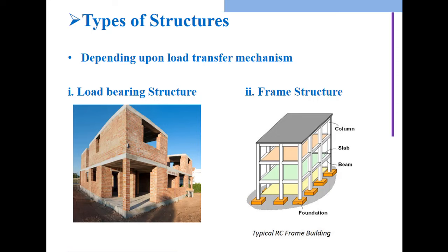Right? So as I told you earlier also, if you want to determine the weight of the bar in kg, you need to remember the formula, which is diameter of bar squared divided by 162.2. Why am I talking about these things? Because whenever you are going to assign the dead load, these things are very important. If you only select the dead load for the overall building, does it contain the weight of the bar? If the weight of bar is not considered during the analysis of the building, it means you are not considering the 25 percent of the steel weight load. Okay, that is very important.